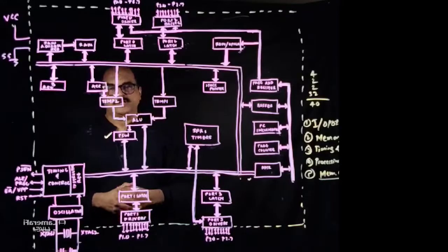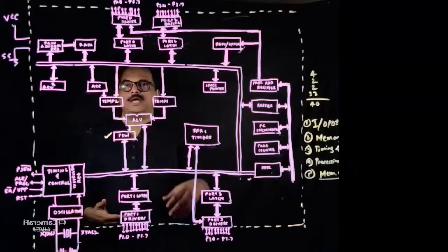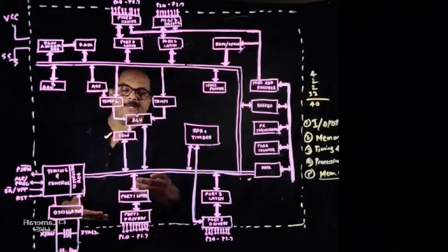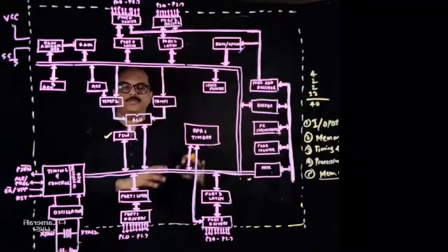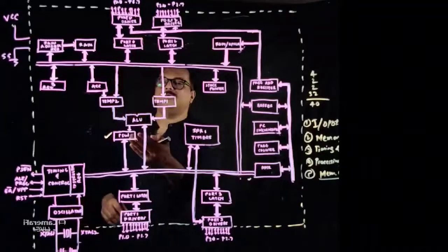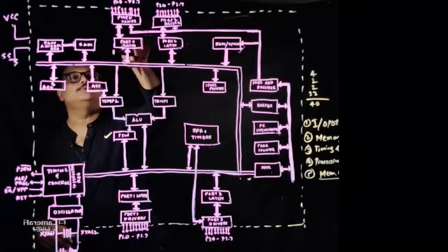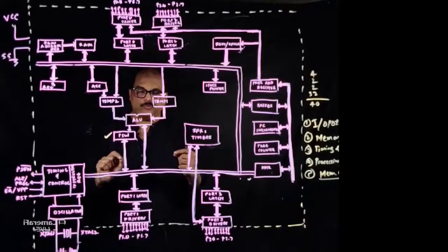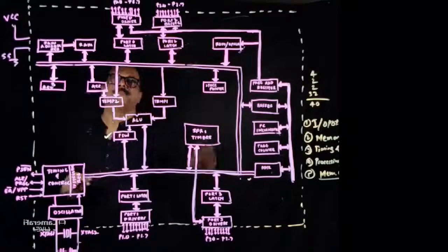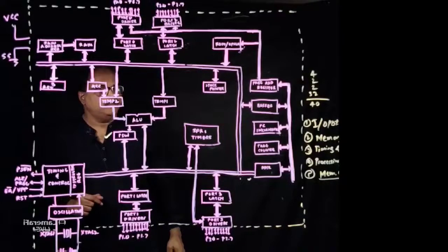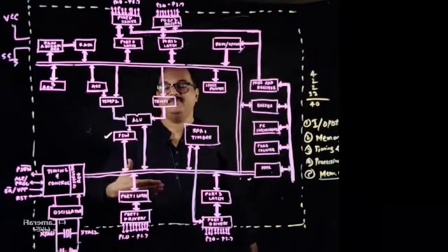So when you have to output certain data on any particular port, that data comes out from your accumulator, suppose, and then you write it on the port. Say for example, your instruction is move P0 comma A, where P0 is the port over here. So from the accumulator you want to transfer data to port 0, so it first goes to the latch, and the latch is the circuitry responsible for storing that value, and then that value is taken out to the port, okay. Now obviously every port will have a latch, and it also will have a buffer.